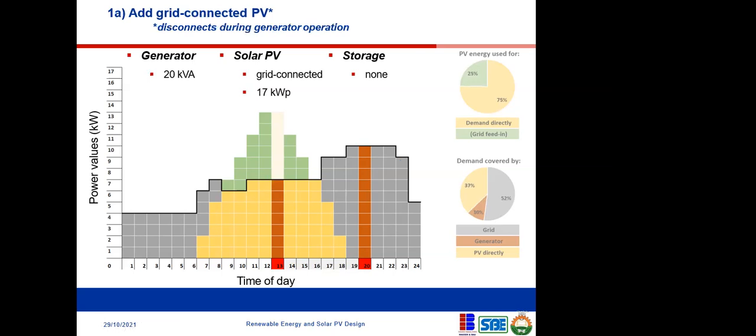Whereas in this case, if the grid fails and the solar doesn't have enough capacity to supply your consumption, what happens? The inverter will just knock it off. It will not even take anything from it, right? But whereby you have a hybrid controller means that it can collect power from the generator and also collect the one that is coming from your solar, even as much as the grid is not there.